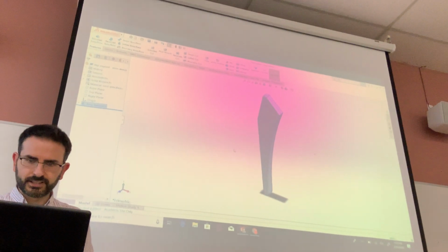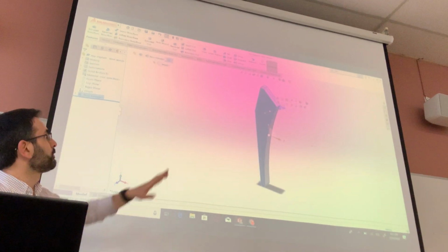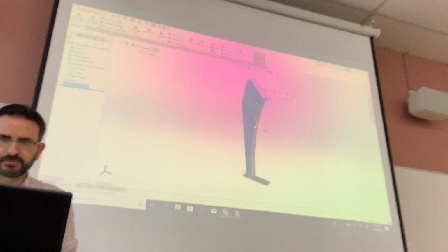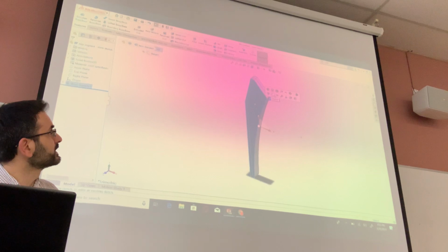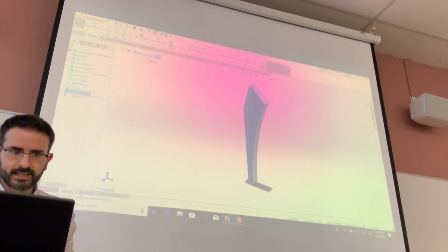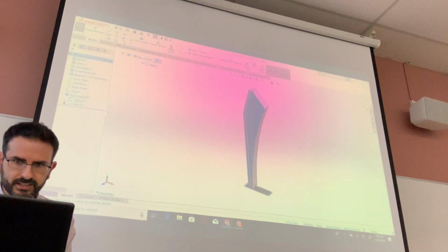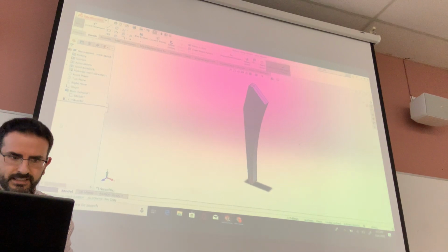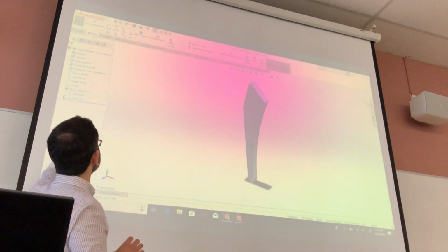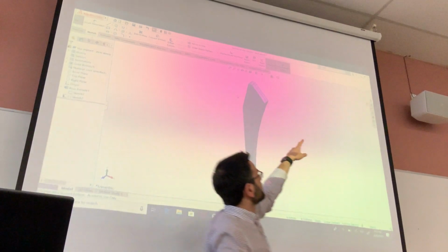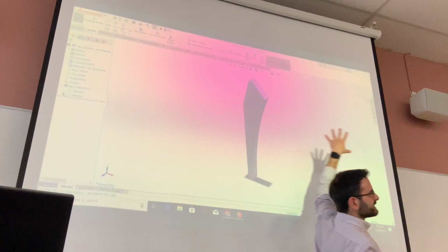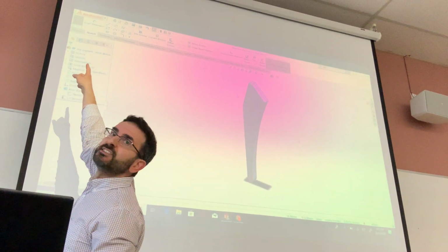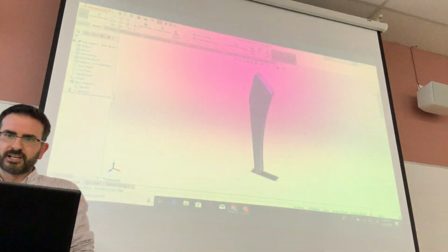Now, next thing to do here, we can select this face to create another sketch. Select this face here and say, create a sketch on this face. And the other thing I need to do is to make this sketch that's already visible, so it's already good. And in the new sketch, so right now I'm in sketch number 2. You see it's open here, and there are those buttons there that tell you that I'm in editing mode, which is also confirmed by the top corner there, where the editing mode is clicked down.